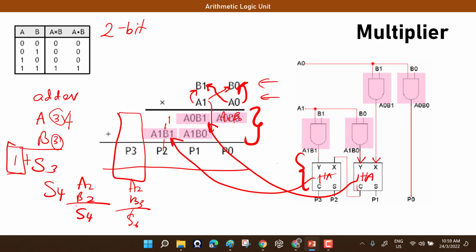This process here is actually a carry out coming in over here, so a half adder is sufficient; you need not have a full adder. But if it involves 3 layers, the half adder has its limitation. If you want to use half adders, you need to do what we did in the previous exercise: cascade 2 half adders to become 1 full adder.